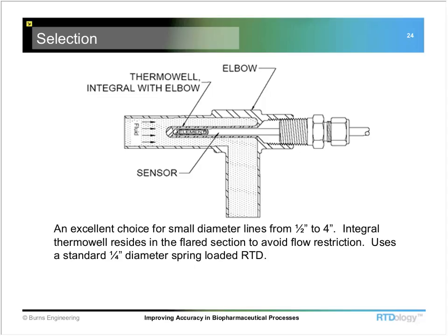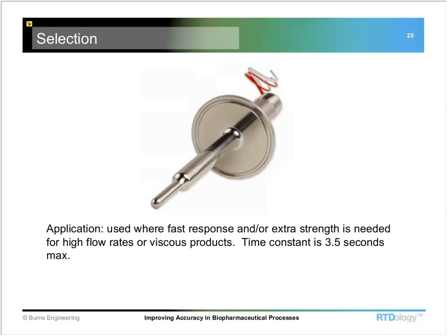And if there's a situation where you needed the time response improvement, that can really make a big difference. One of the other ways to do this without the heat transfer paste is to use a sensor that has a small copper tip on it, so it has a little better heat transfer as it's bottomed out right against the bottom of the well. Stainless is actually a very poor conductor of heat, so having that copper tip on the probe and the sensing element potted inside of that can be another potential solution there.